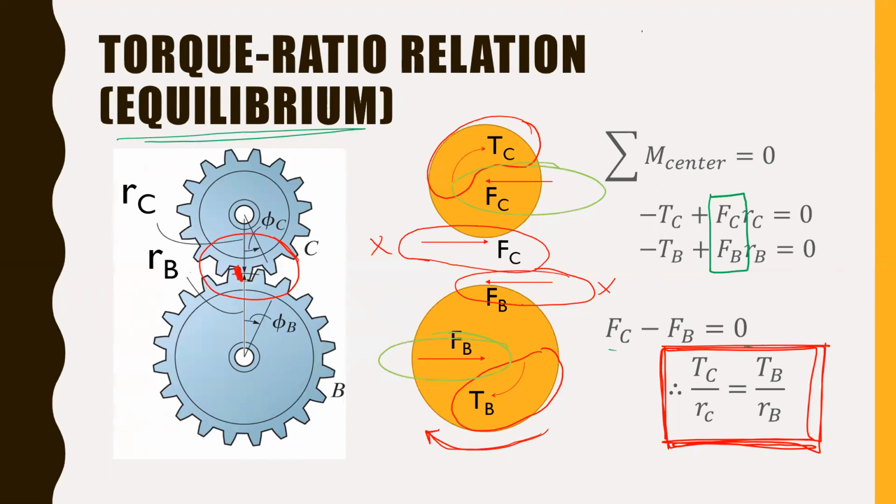Okay, so everything made sense, but the reason I show these here is because I'm just foreshadowing later, when we're going to be designing our shafts. It's not as simple as just looking at the torque on the shaft. If you get this reaction due to the torque in the horizontal direction, and you're just looking at this gear, that gear has to be in equilibrium. If I neglect that force at the center, it is not in force equilibrium.